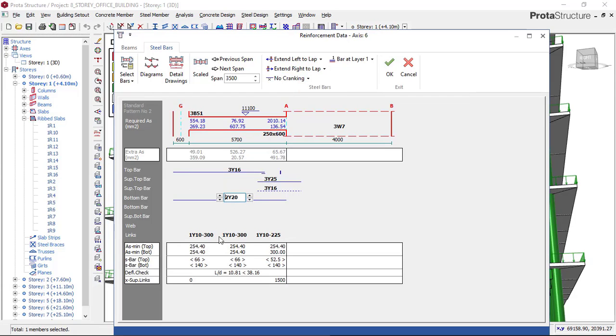And if there was failure on this link, I would say that you should go and increase your depth of beam, because that's what causes the failure. If your depth of beam is too small, you have to go and increase your depth of beam. In my coming video, let me say by September, I'll show you guys how to adjust these links when there is failure. I'll make the structure fail in terms of links, and then show you how to adjust that.